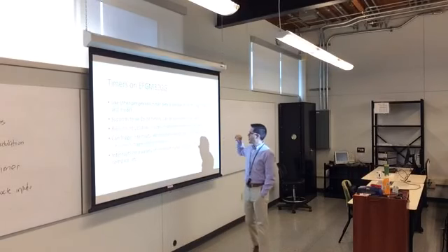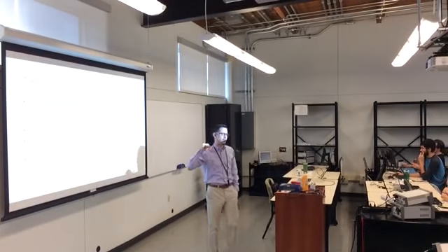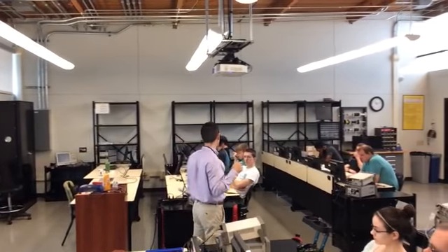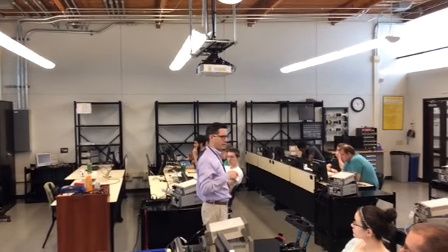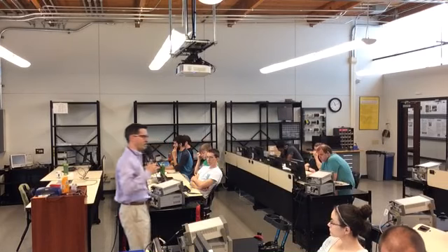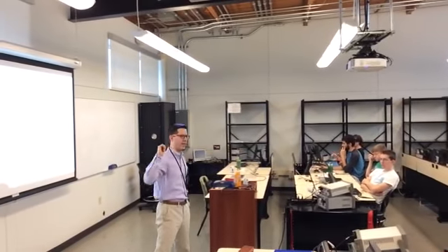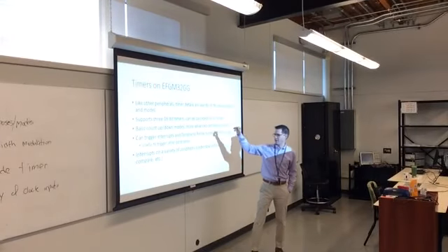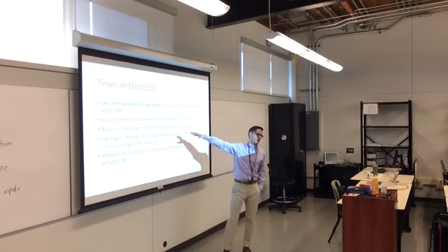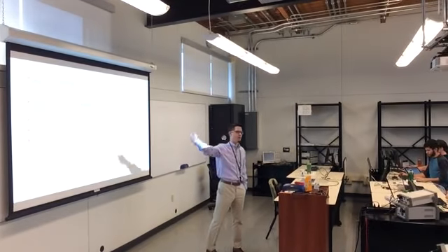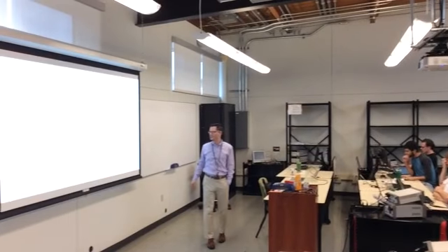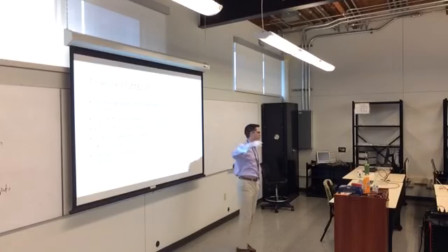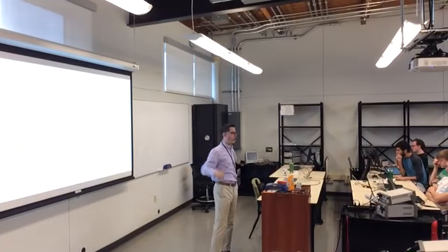Another thing is that the timers are only useful if they can trigger an interrupt. We will start to talk about interrupts at the end of this lecture. You really don't want to set a timer and just sit there and go, did you reach the number? Did you reach the number? You would really like it to go off and do some other business, and then when it's done, let you know. That's the major purpose of an interrupt. It can trigger an interrupt to the processor. It can also trigger something on the peripheral reflex system such that it talks to other peripherals, so the processor doesn't have to be involved. You can set interrupts on a variety of conditions: underflow, overflow, comparison between the timer and a fixed value. There are lots of parameters for these timers.